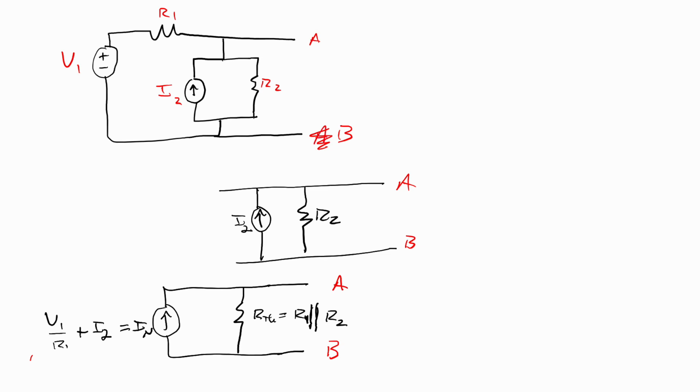And so how to simplify this, that's kind of a pain, because we've got something in series and we've got something in parallel, and looking in here, it's a nuisance. It's a little effort, but it's not too bad. In fact, if you look at this, you can realize, oh, right here, this is a Thevenin source. If I converted it to a Norton source, maybe it's a whole lot simpler.